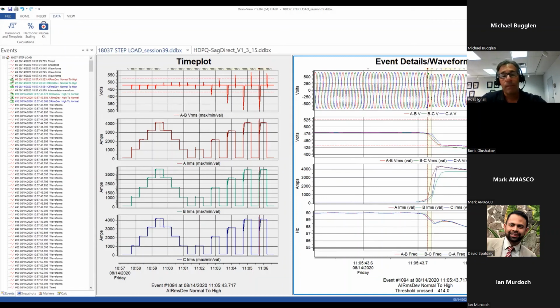That's critical. I can't judge whether this is pass or fail in this situation. I don't know the requirements for this application, but looking at the power quality, looking at the reduction, the sag, and any swells that have occurred and the effect on the frequency, it kind of pulls this all together on power quality monitoring for a very, very real world application here.